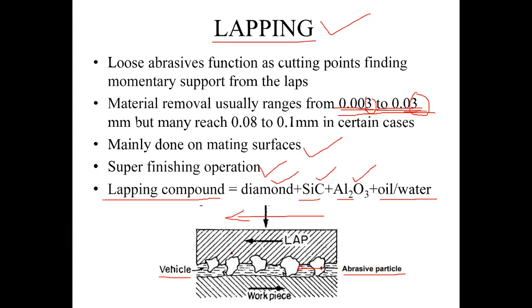But in some cases, what happens? These abrasive particles may be joined with this abrasive tool, so you can directly sprinkle them on it. When you sprinkle on this, the abrasive particles stick to the surface. Using these sticking abrasive particles, if you rub on the surface, it removes the material from the uneven surfaces. So this is called the lapping process.